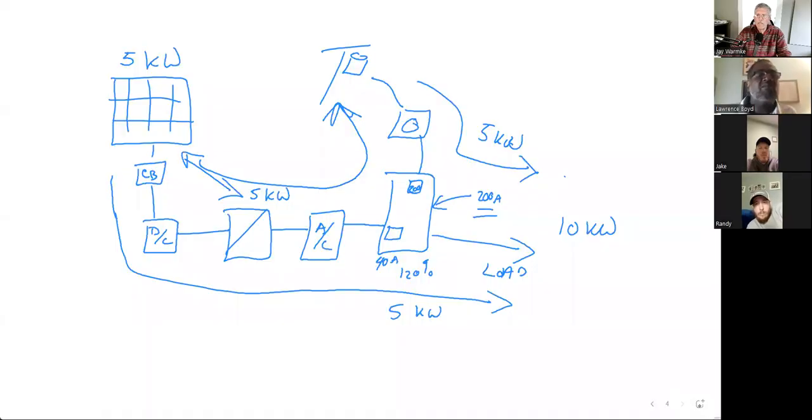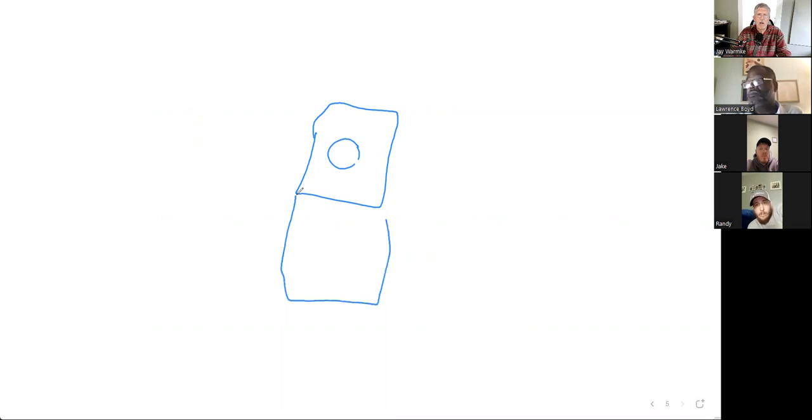Okay. Yeah, the way that works, let's see, if I go back to my screen share, I'm using the whiteboard quite a lot. Typically you've got a meter box here, and then with the newer systems, you're going to have what looks like a small circuit breaker box underneath of it. There's going to be a main disconnect here, and then a couple of 240 breakers down below. This is now considered your main, and it's considered the main utility disconnect.